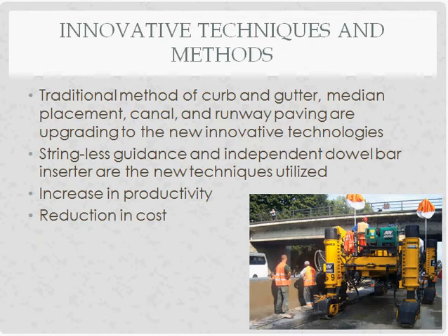Some of the new innovative techniques, methods, and applications for slipform paving. It's graduated from the normal roadway construction and has moved into the curb and gutter construction, median placement, canal lining, and runway paving. Some of the new techniques utilized are stringless guidance systems for the slipform pavers, as well as independent dowel bar inserters.